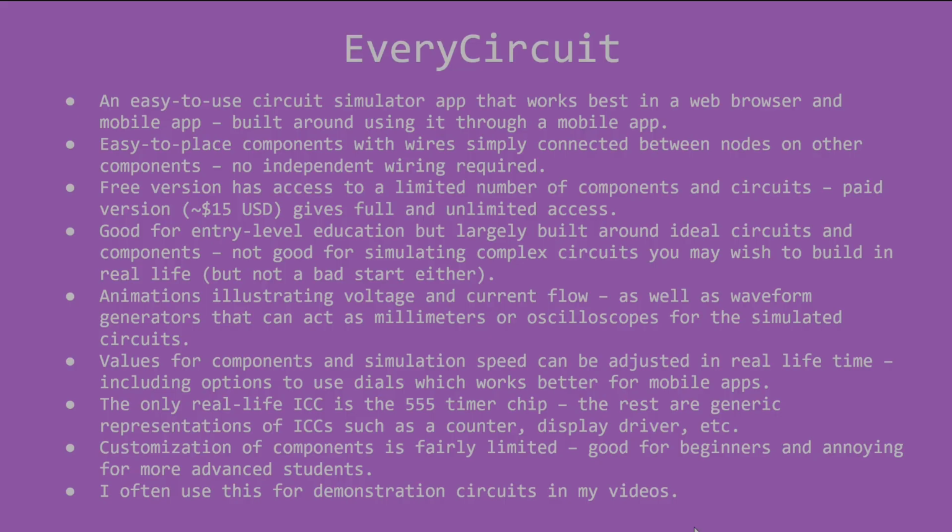You simply click on one node, click on another, and then it puts a wire. That's the upside of not having to place the wires, but the downside of not having any real control on how they are routed. I highly recommend this for entry-level education, again, based on my own personal experience, keeping in mind that it's dealing with ideal circuits and components and isn't really good for simulating more complex circuits. You should also be wary of using it as a blueprint for real-life circuits, but again, it's not a bad place to start. It has some nice animations illustrating current flow, LEDs, etc.